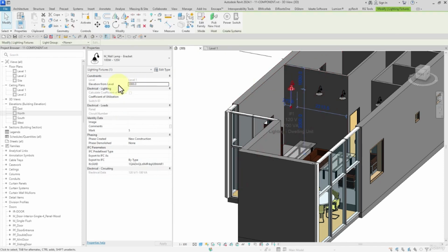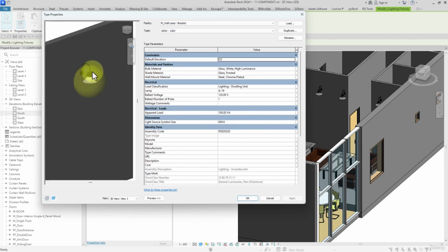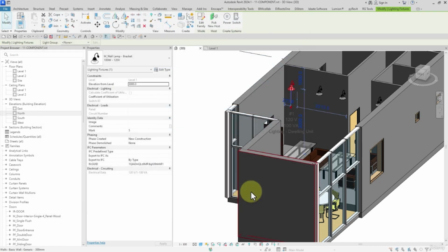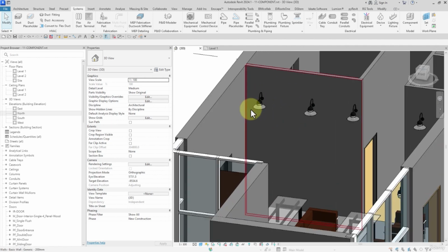Actually, you can find the related instructions in the electrical installation course, and others are repetitive. And then in the type properties, as you can see, for the lighting fixtures, we got the geometry itself, and also the radiator, or the emitter of the stream of the light that is not visible by default in Revit.